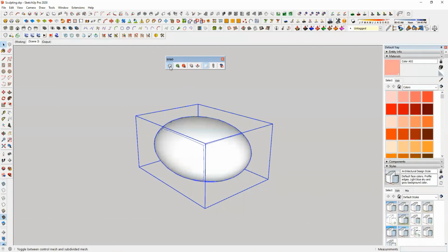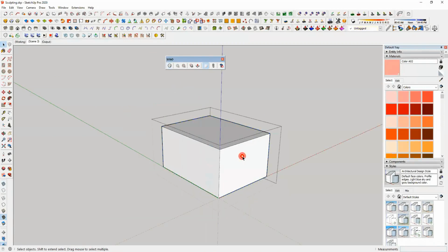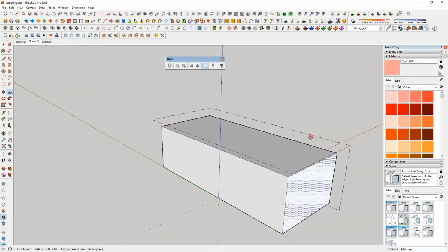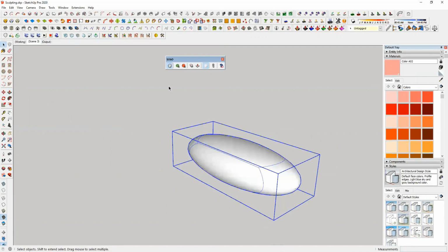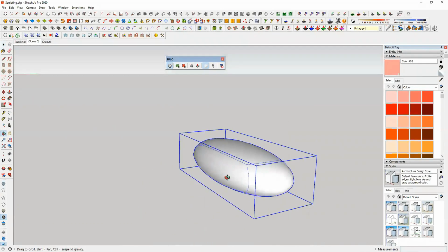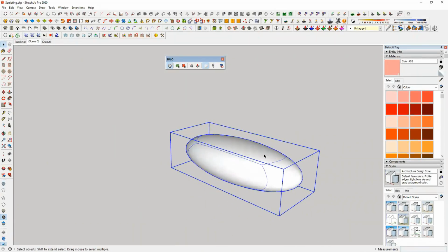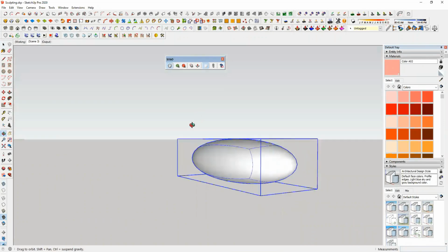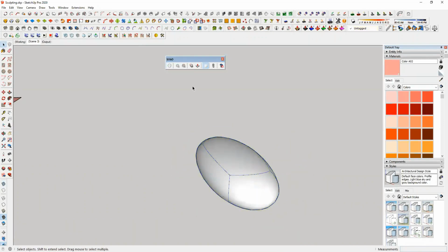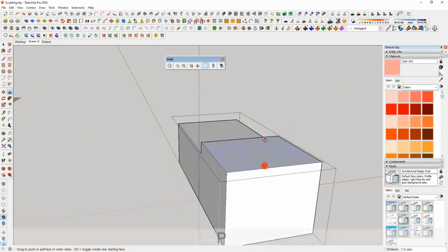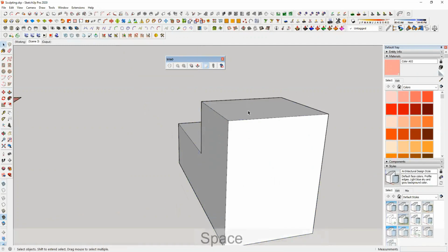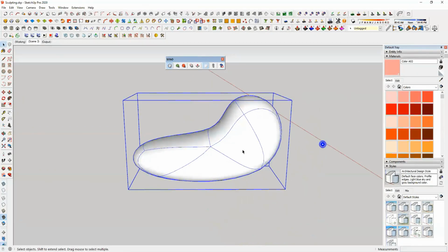At any point, if you want to make some changes to the original shape, you can just go ahead, make some changes, and again select the cuboid or the group and click on the subd icon. And thus you can see that we have the changes, but at the same time we also get the organic geometry. So let's turn it off and add some more divisions and pull this on the top, and again turn this off.